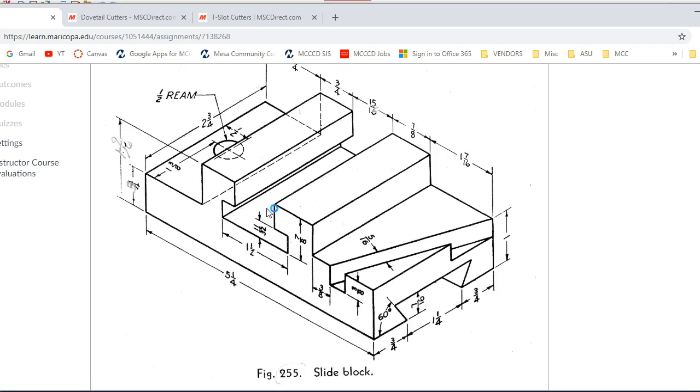Of course, we'll be taking an end mill and roughing through, so this would be a good place for an area clearance, having the two individual chains, so that it can nibble through there on the trochoidal. It could also be a pocket where we overrun the ends. Either one of those will get that opened up to where then we can bring the T-slot cutter in and make several passes, and with enough extension make sure that it clears so that we can generate the slot.